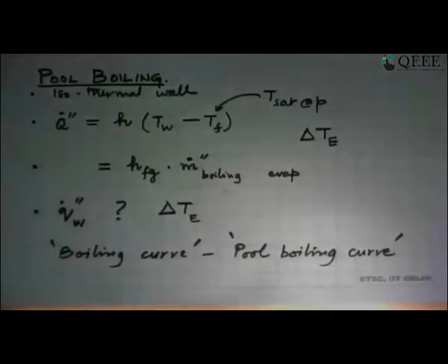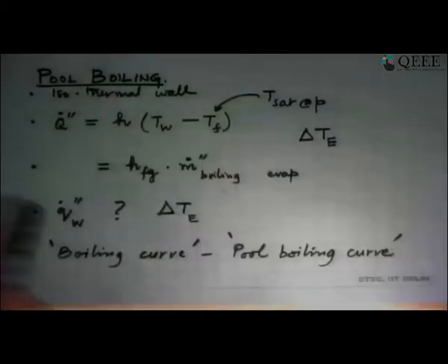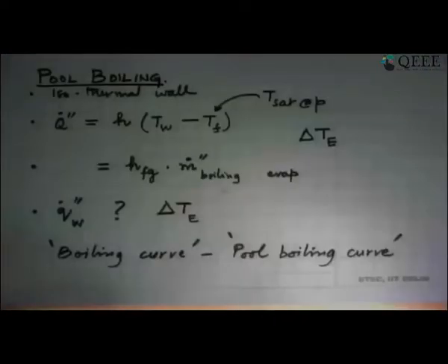And remember that in the context of the applications I have just mentioned, pool boiling is a very limited family where directly taking the result and applying it has a degree of risk and uncertainty associated with it. So we assume that the wall is isothermal. Let's begin with that particular case, what we have called in convection heat transfer the isothermal wall, the T case.